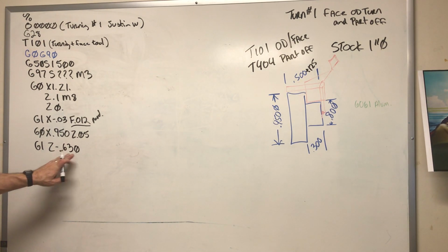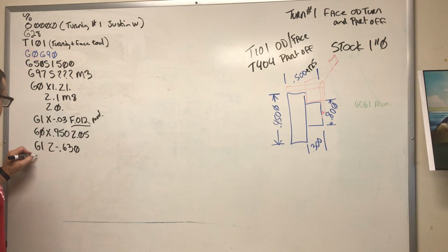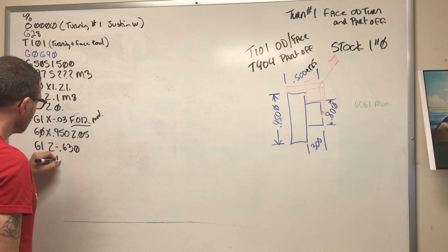So at this point, I've faced it off, I've turned my diameter back. I'm going to go ahead and just feed up this face. So I'll go to X 1 inch.